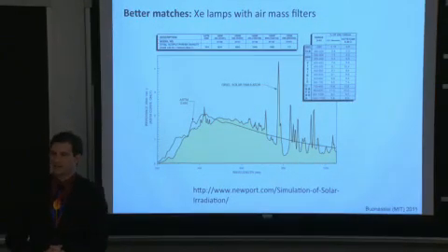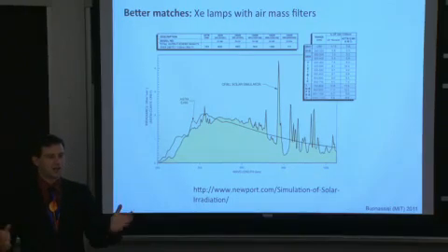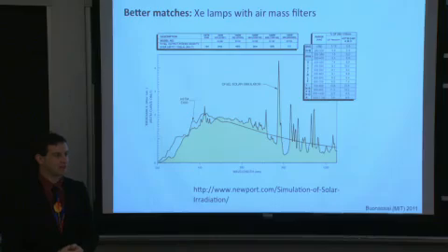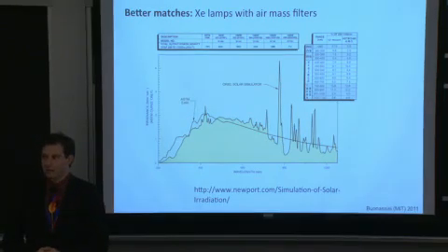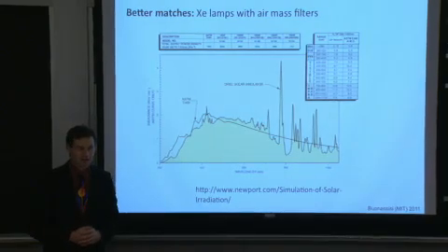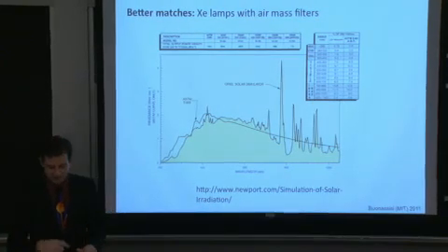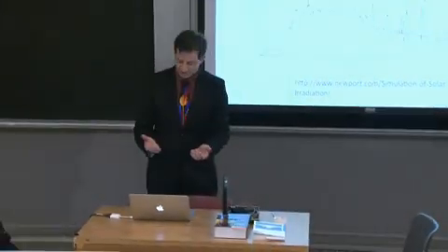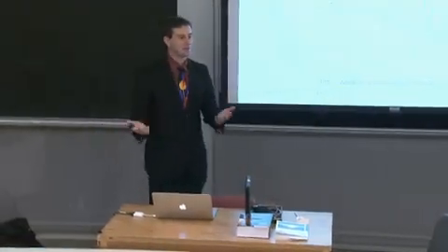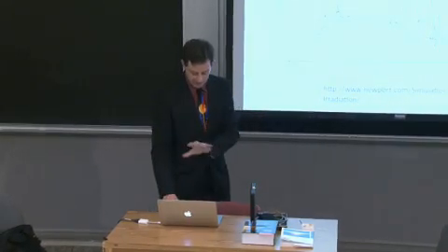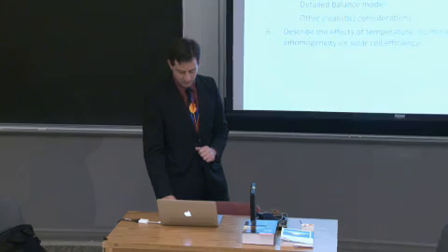But then when I stick my cell in there, all of a sudden I'm getting a super high efficiency. I just made an organic device and my efficiency is 11%, which would be a world record. I'm ecstatic, I'm really happy, until I do the quantum efficiency of both the standard calibration cell and my new cell, and I realize, wait a second, they're nowhere near each other in terms of their responsivity, what region of the solar spectrum they can respond well at.